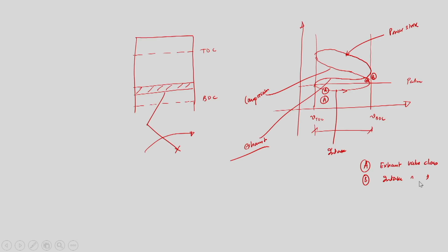So, with the piston departing from BDC towards TDC, we should not close the intake valve immediately, because we have just seen that we are allowing the exhaust valve to remain open for a small time even after the piston is traveling from TDC towards BDC. So, some part of the charge or air will go out with the residue of the combustion product. If we do not compensate that amount of air or charge, combustion will not be efficient.